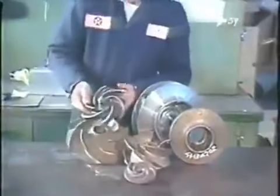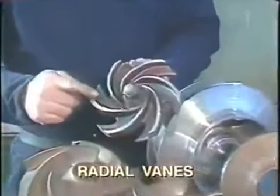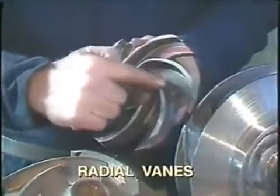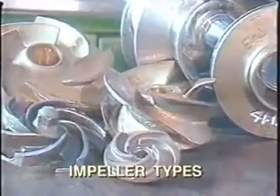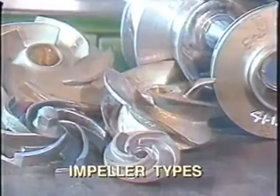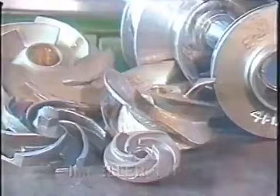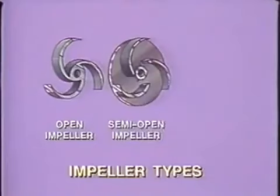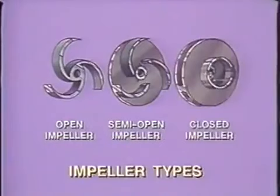A second classification is made by the shape of the vanes. While there are some variations, the most common by far is the radial type. Impellers also vary in their mechanical design. There are three basic types: open, semi-open, and closed. An open impeller basically consists of nothing but vanes. A semi-open impeller has a back wall called a shroud and is closed on one side. A closed impeller has a shroud covering both sides of the vanes. It's open only at the suction eye and closed to the tips of the vanes.